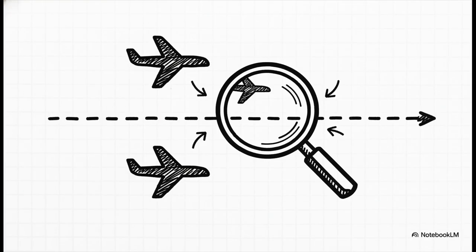But listen, this is where your situational awareness needs to be incredibly sharp. Because these CA or VA legs often involve altitude terminations, you have to remember that your aircraft might or might not already be at or above the specified altitude when that initial leg actually sequences in the FMS.